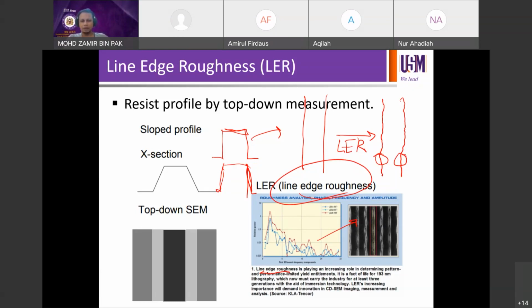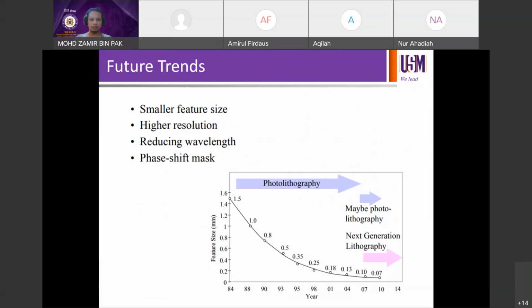Okay. On the other hand, if your intended CD is like 10 and then your roughness is 5, and that's like half of the intended CD, so that can interfere. Okay, interfere. So that means when you measure here, the algorithm is looking for 10, but it's finding 5 as well on the side. So they're complaining. So that's why at that particular point, when you go for state of the art punya chip yang high end punya, yang 7 nanometer, 5 nanometer, you cannot tolerate the very same magnitude of the roughness on the edge. Okay, so how to solve this LER issue? I'll leave it to you.